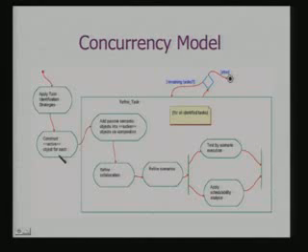In fact, these active objects can also translate to the subsystems in the global system. So you construct an active object for each, and add passive semantic objects into active objects via composition. Why passive semantic objects? There may be components which are to be controlled within a task. So there may be an LED indicator. An LED display or LCD display will be a passive object under the control of a task. So I can put that as part of your active object through composition.